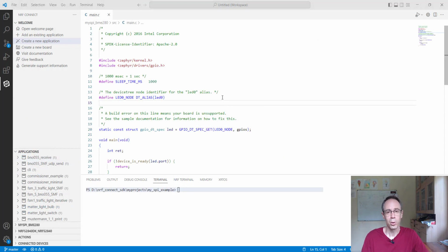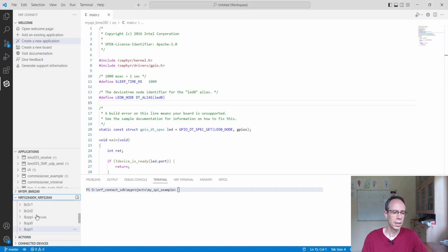When the build is done, the first question which arises is of course how we connect our BME with the nRF SDK. This we can look at here in our Visual Studio. There we're finding the resources. When we're looking here, we will use SPI1. And you're seeing here there are the MOSI, the clock line and the MISO line. So we have here the MOSI at GPIO 0, pin 30, the clock line at GPIO 0 and pin 31, and the MISO is at GPIO 1 pin 8. Here is no chip select. We will make this manually.